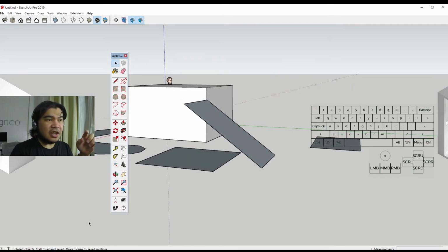You can see here at the bottom left position, there is some sort of status area where, when you identify a command, let's say rectangle, you can see it's asking us to select the first corner, and then control. Holding down control will allow you to select the center instead.